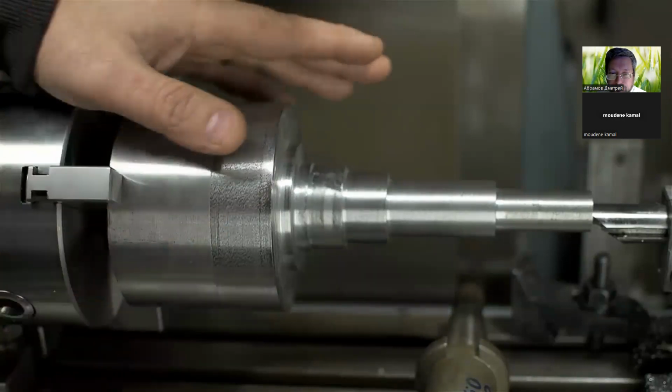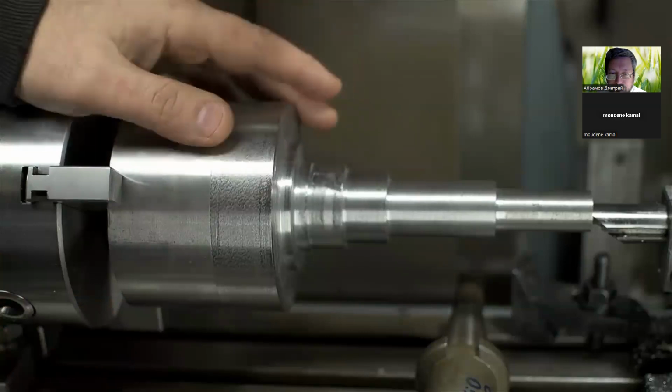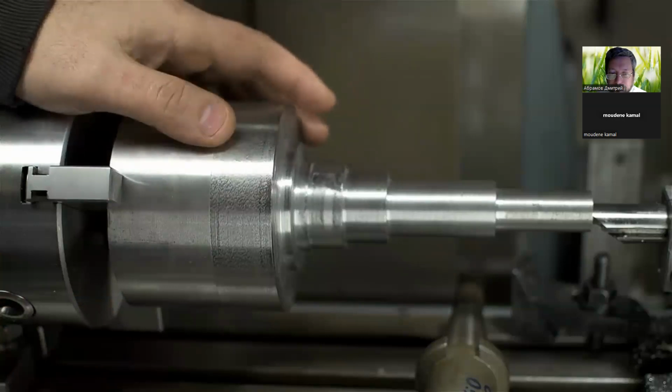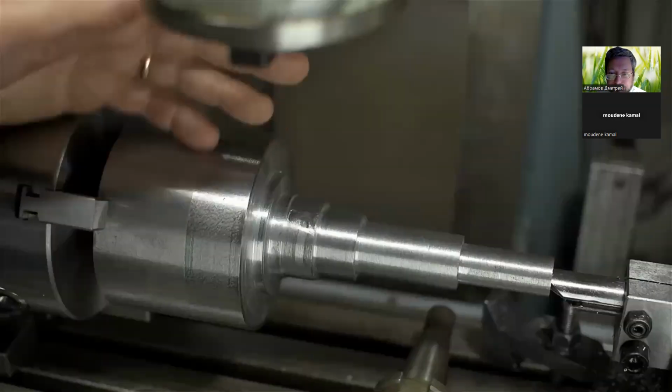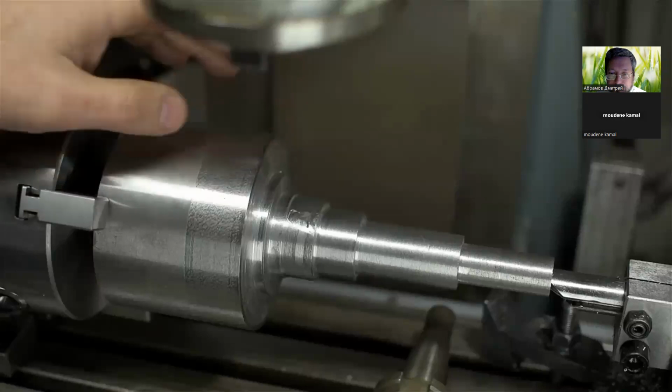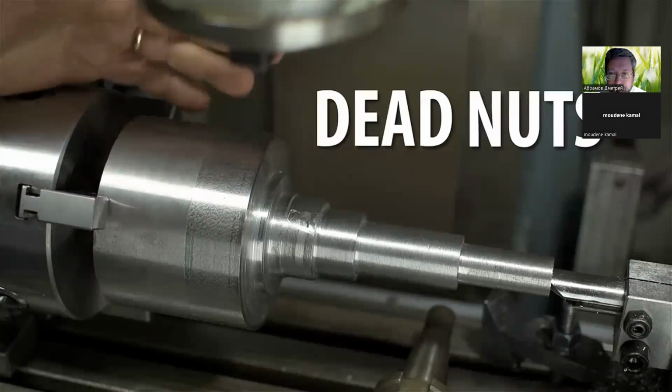But they either went to town on this and took their measurements hot, or they used an older, worn PTO to figure out what the dimension should be. In either case, our major diameter is now undersized. What does that all boil down to? Well, I'm not going to volunteer for the extra work to get this thing dead nuts, or in metric, spot on.